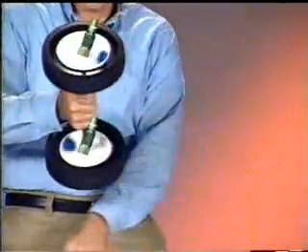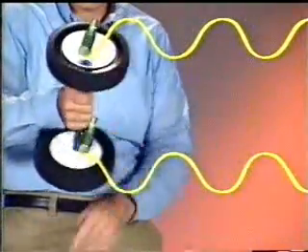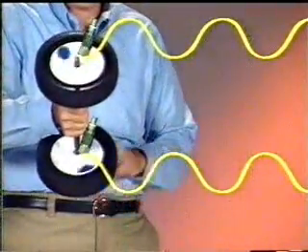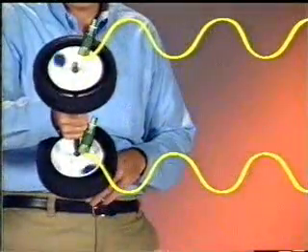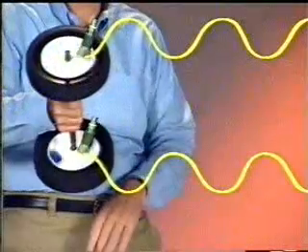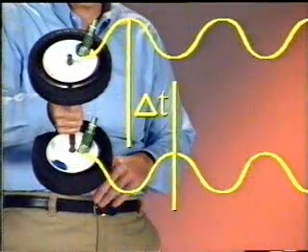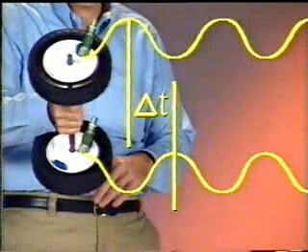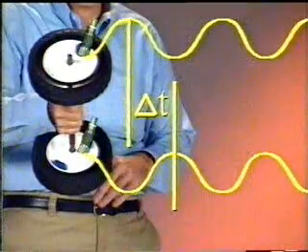Essentially, it performs the same function we illustrated with the two sine waves from the unbalanced wheels. That is, it compares the peaks for a particular frequency to determine if they are in phase or out of phase. The time difference is calculated to determine the exact phase relationship between the two.